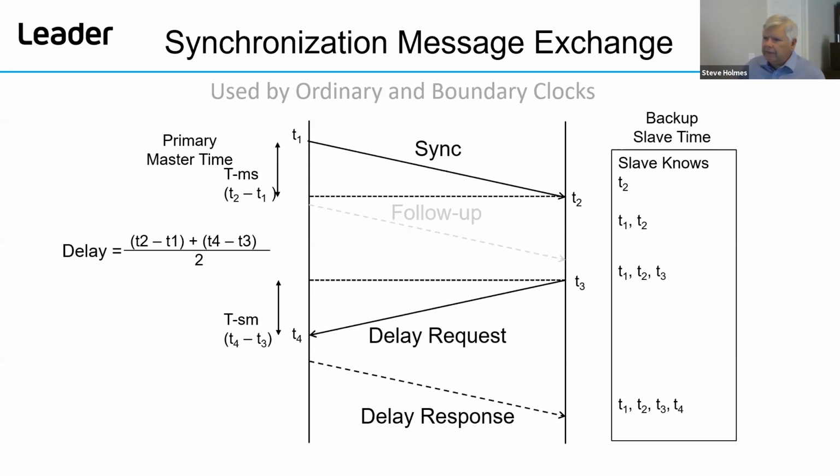By dividing by 2, you get a two-to-one average, a little better average, and the slave will now know how much time to correct. Since we are syncing oscillators, it can't just yank itself to that point in time instantly. You're going to see messages come in, and it's going to slowly pull that time in within a matter of a few seconds.